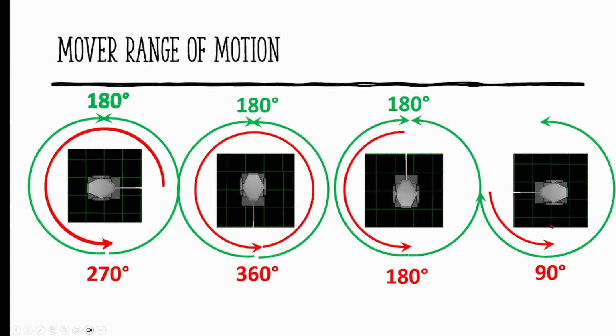So now I'm pointing forward. If I wanted to go this way and go all the way to the back, I can't, because I hit a hard stop. I can go this way, but I can't go this way. So I sit there and say, okay, what happens if I spin 360 degrees around and then I come to the front? Now I can go this way, but I hit the 540 limit on this side, so it will only spin to here and stop. I've hit the full range of the light, so now I can't go back this way.